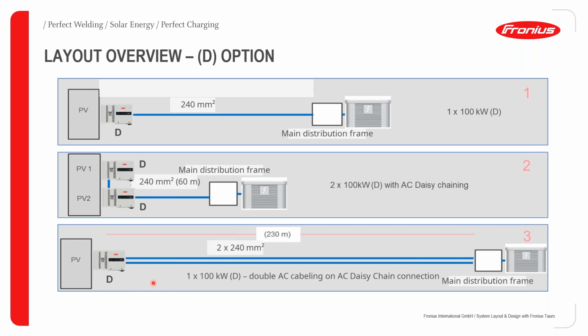so the less losses there are. So if you choose to use the AC-DC chain option, so remember the AC-DC chain option has 10 outputs on your AC connection, okay? It's got 5 for your first AC connection and 5 for your second AC connection, okay? So in this example, I'm using the AC-DC chain option in order to cut down on my losses due to the wide distance from the inverter to the transformer.